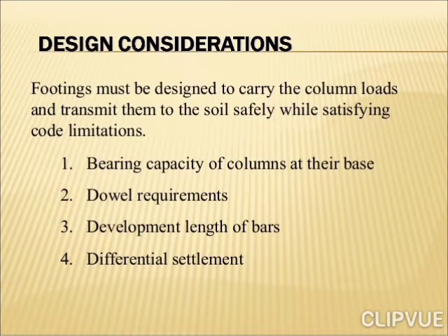Design considerations for a footing. Footings must be designed to carry the column loads and transmit them to the soil safely while satisfying code limitations. Bearing capacity of columns at their base. Dowel requirements. Development length of bars. Differential settlement.